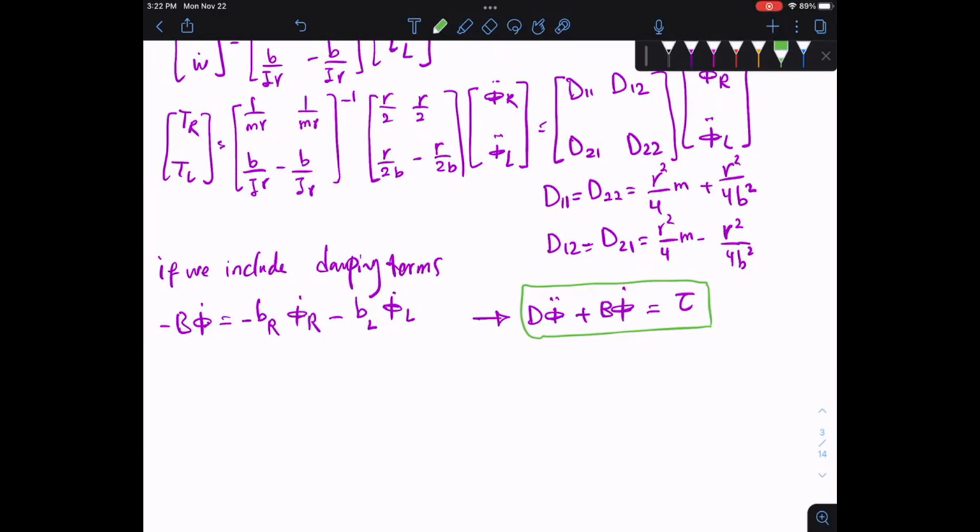So when you're writing the controller, you go back to where we had the DC motor block diagrams, all of those, right? So right wheel, left wheel, and then you can control the system. Really from here, you have already done it. So usually coming to the equation, you see that it usually becomes a second order system and you should be able to do it for any system, right? So your job is to develop that. So usually we use a low level PID controller.